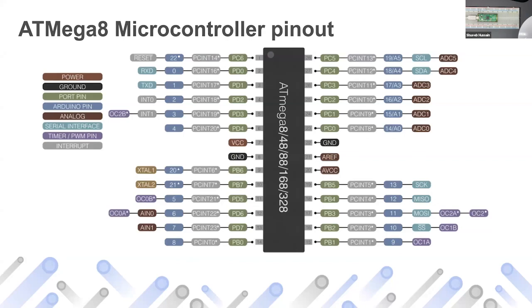So in general, there are two different architectures, right? Harvard architecture and von Neumann architecture. Microcontrollers have separate memories for code and data. Code these days generally sits in flash memory, which can be erased and written like 10,000 times or something.